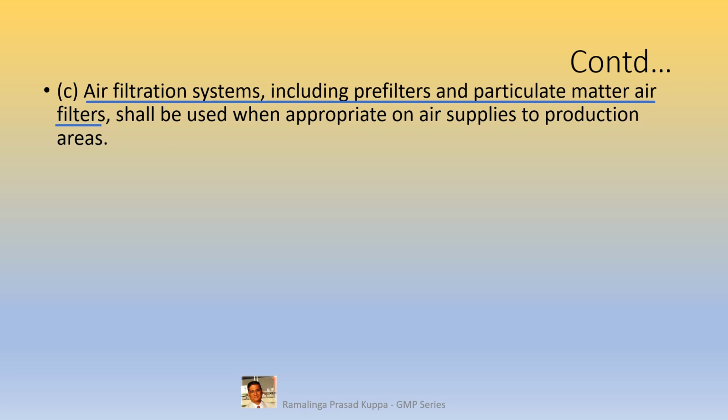So, for example, if there is a 5 micron end filter, it is necessary to install another coarse filter of 10 microns capacity before the end filter. A 20 micron capacity filter may also be installed before the 10 micron filter to reduce the filtration load further.